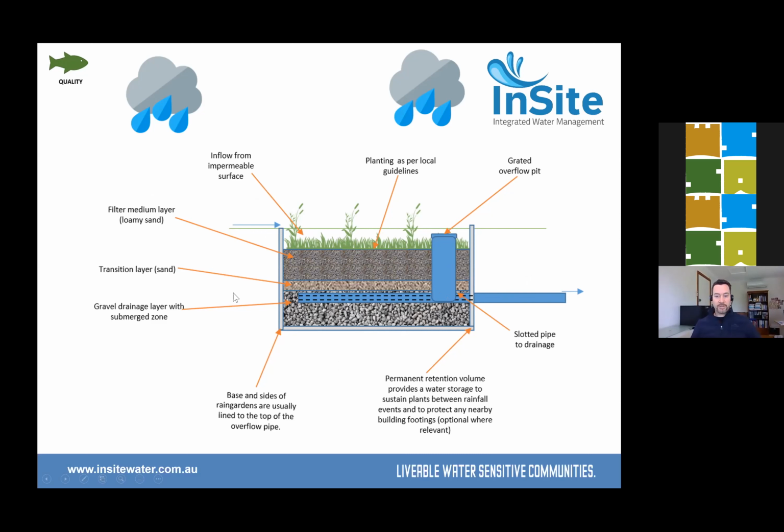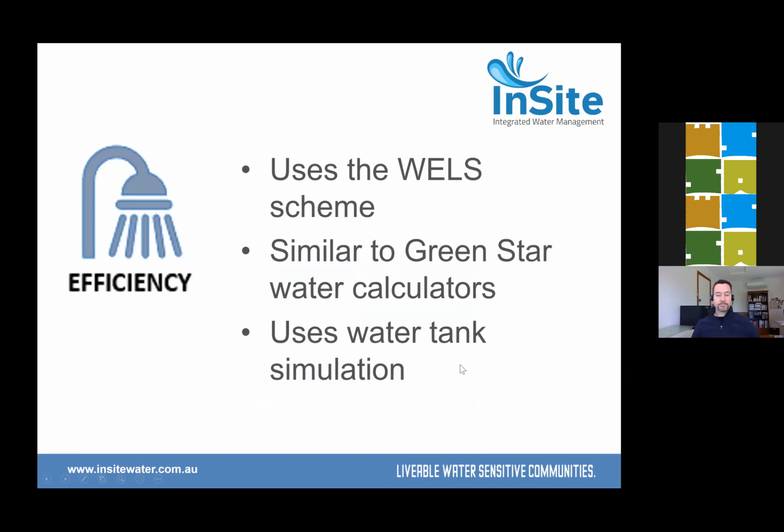And there are lots of different designs for rain gardens and bioswales, but we've put some suggestions, I guess, for minimum standards, such as having an overflow pit, into the tool.